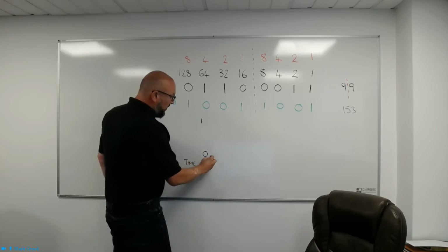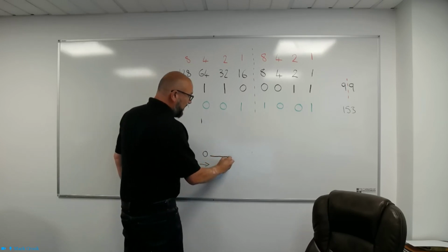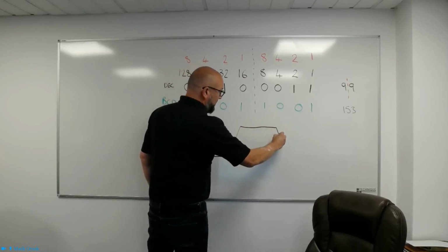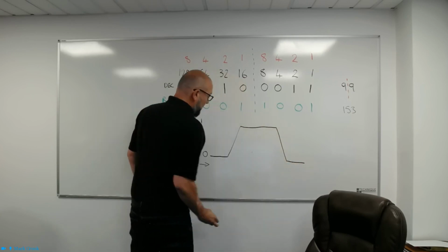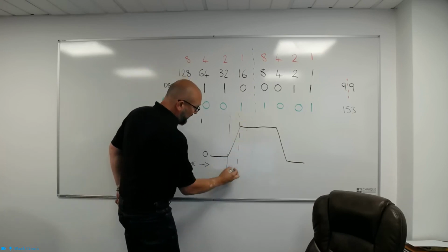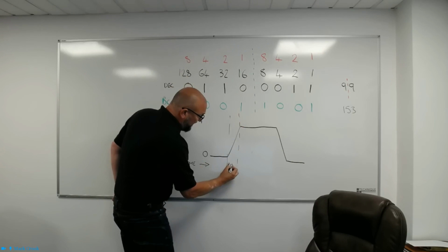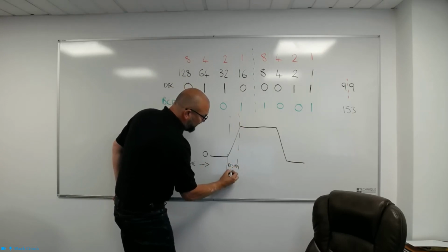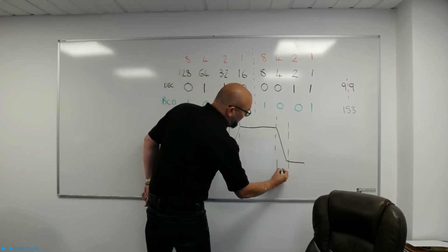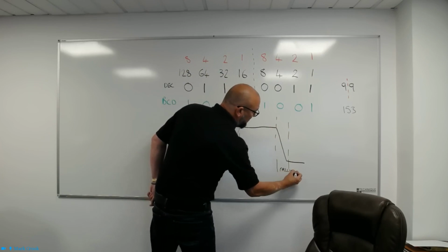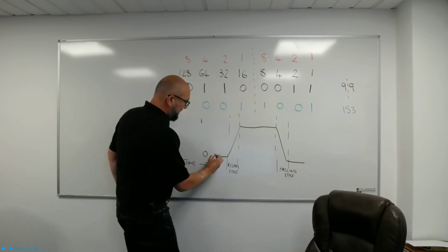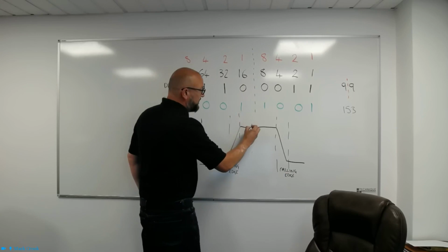Okay, so if we've got a button switched off, it sits there in time, and then when it comes on, it triggers, it stays on while we've got the button energized, and it goes off like such. Now, the important parts to this here is this bit here first of all. That is called the rising edge. So that's when something is being triggered positive. This portion here is called the falling edge. So that is when something is going from positive to negative, as we call it, because this is negative, where actually it's at 0, and this is the positive.